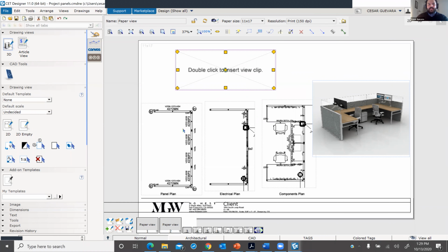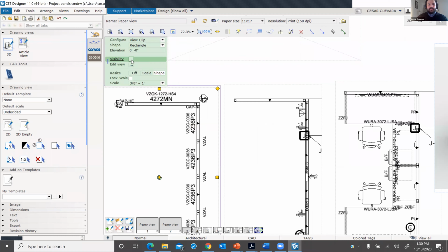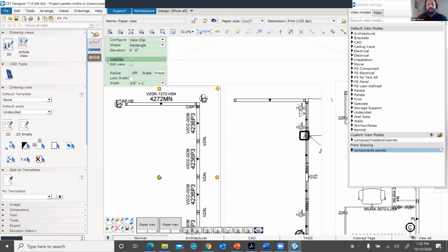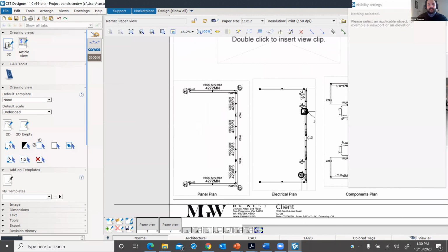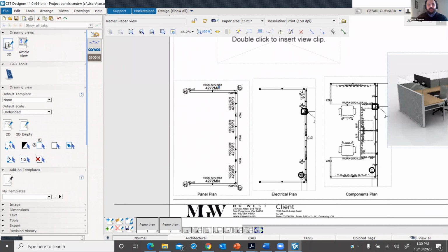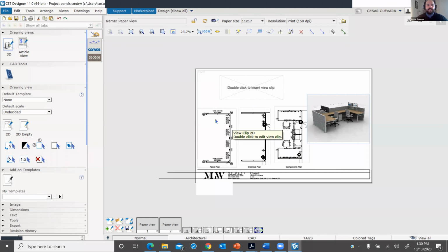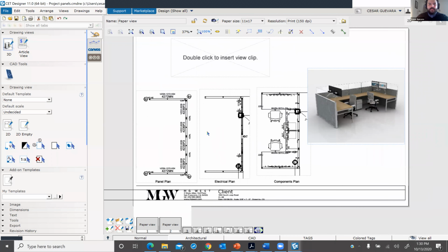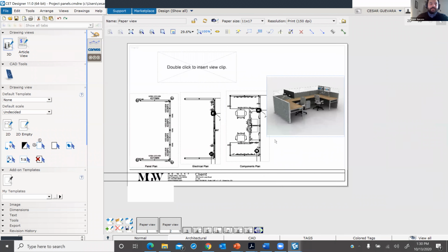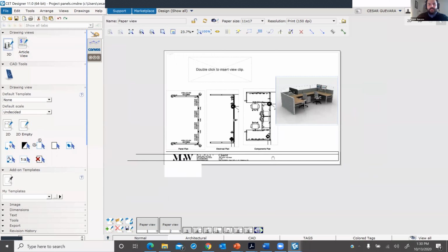If they want to add or delete some things, then all they'll have to do is go into visibility settings and edit that one and save it as a different name. Sometimes you'll have to do that anyway because maybe there's something unique. So remember, having a reusable drawing saves time if you already have it.